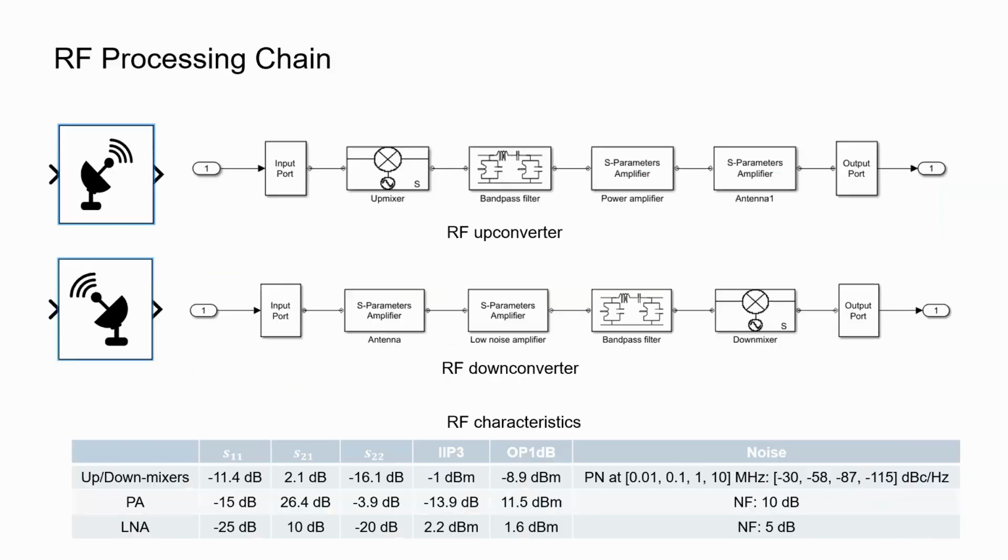Additionally, I'd like to introduce the RF blocks used in this work. The RF devices are responsible for frequency modulation and analog signal transception. Both the transmitter and receiver side include a mixer for frequency conversion, a bandpass filter, and an amplifier.